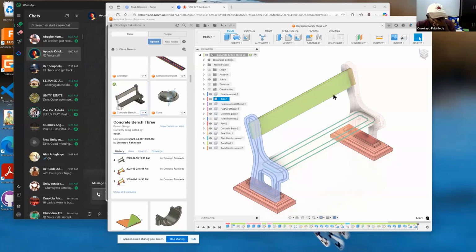And if I created one circle and I want to create another circle, I can go back and pick the icon to create it, or I can remember that there's a marking menu that I can automatically instantiate to do it. But let us not talk too much. Let us just start by creating a new sketch.